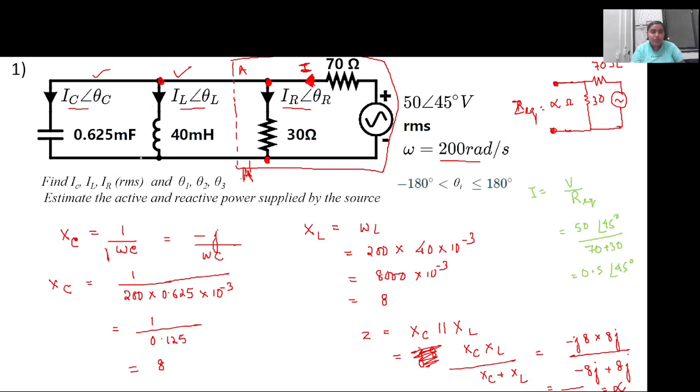This is kind of a situation like you have been taught about resonance, right? There will actually be current flowing through this particular loop, but the source current won't be acting upon it, because it will appear as if there is a very high impedance connected to this particular terminal AA dash. So there will definitely be current in this LC circuit, but it will resonate.